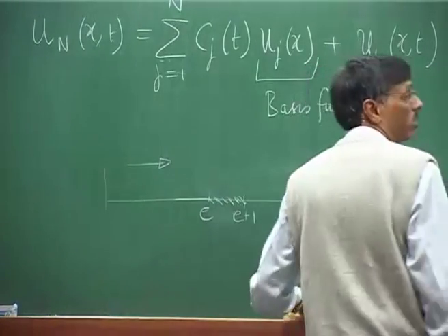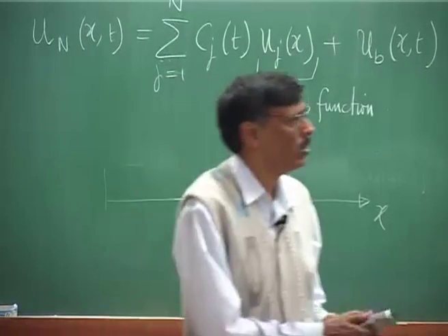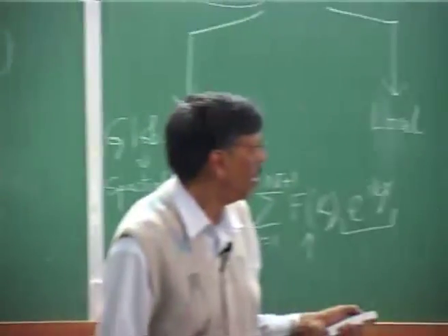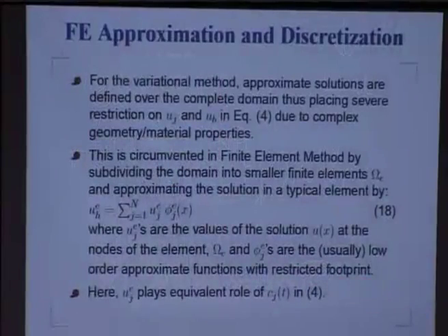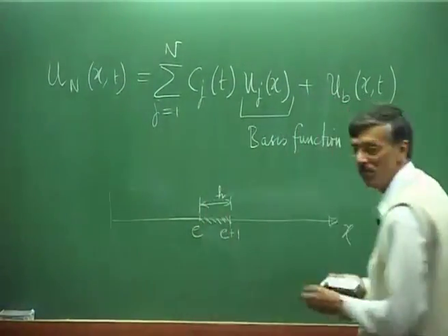Now what we are going to do is, at this element level itself, show that the approximate solution would be dependent on where the element is and what the element size is. We have mentioned that FEM and FVM are favored because you have complete flexibility in choosing that h size. So the spacing between two successive nodes, or the width of the element, is what we are calling h, right.